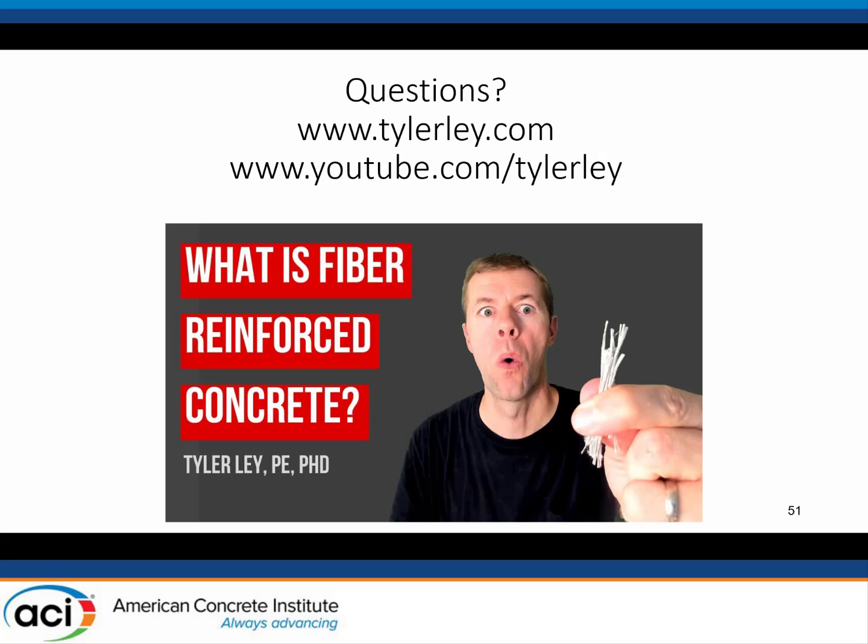Okay, so let me slow down there. So are the cylinders lower strength than what you find on your walls? So these actually happen to be slabs. So they're horizontal walls. Okay, are the cylinders lower strength than what you find in your slabs? Yes. Much lower. So my experience is that that's probably not a sleeve, a plastic versus a wood forms. It's probably not. It may be something to do with the handling of the cylinders, or the curing methods that they use for those cylinders.